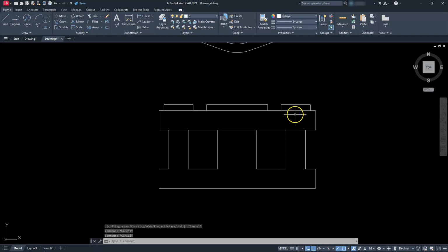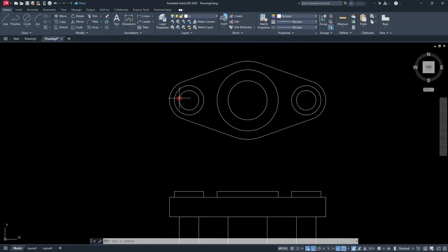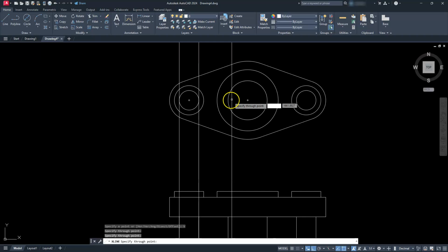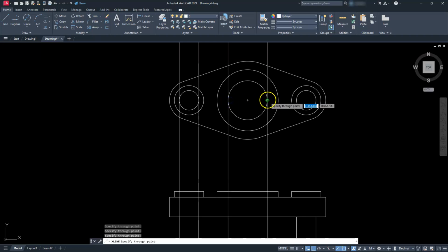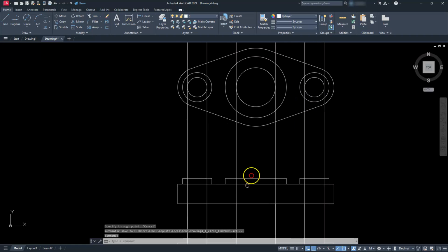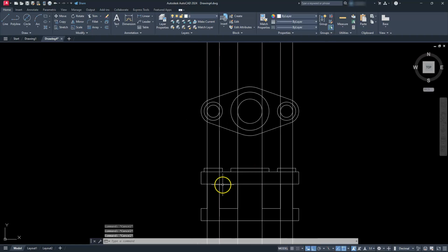So the only thing I need to do now is figure out what those gaps are. Those gaps are located with these inside circles here. So let's go back to the vertical of the construction line there. So once I select that, I want you to go and select the word vertical. And go ahead and select these quadrants. Alright, so once you're done with that, next thing I need to do is go ahead and trim these, right?